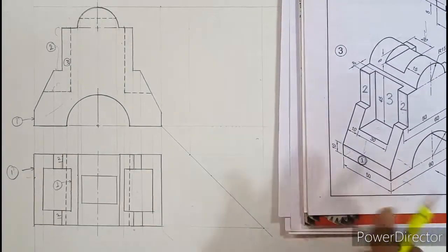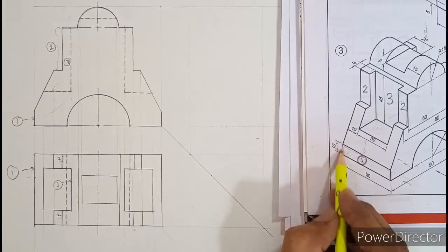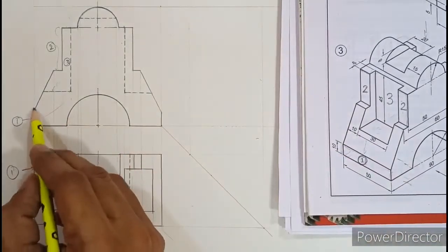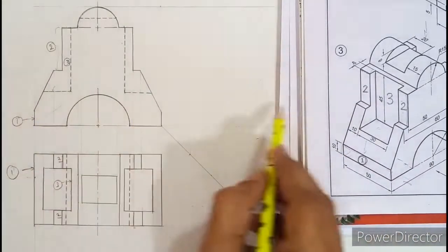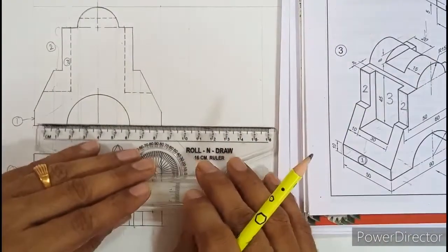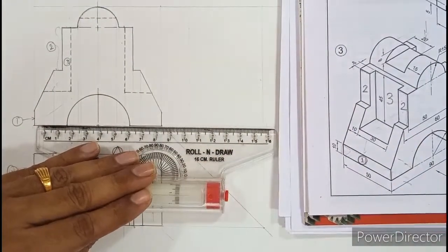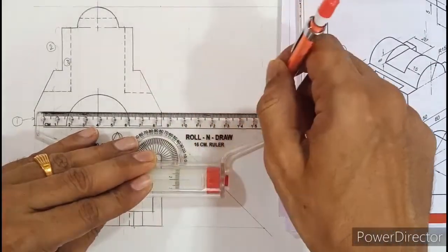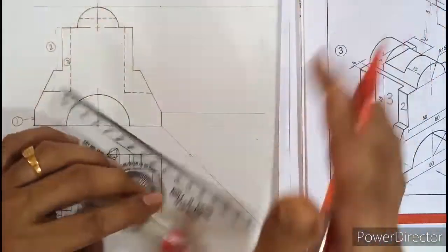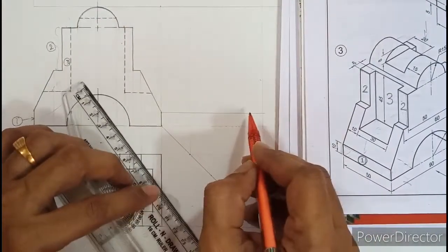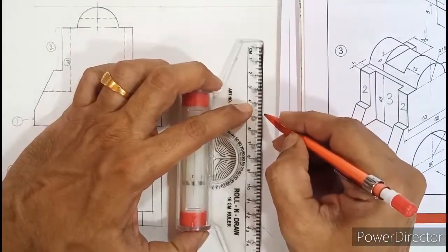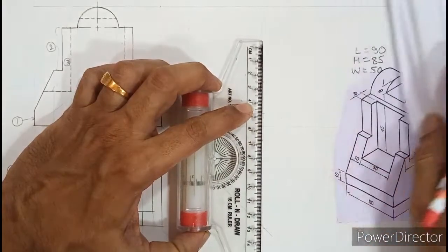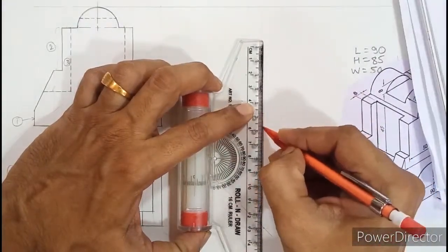Okay, so if you look at this edge number 1, the height is 10. So that same height 10 is here. We need to project this 10 in the side view. So we'll align the scale and we will extend this here. So remember, don't project everything and make a chessboard. What you do is that project one line, one point, darken that out, and then you think about the next part. So I will darken this 10 millimeter width.